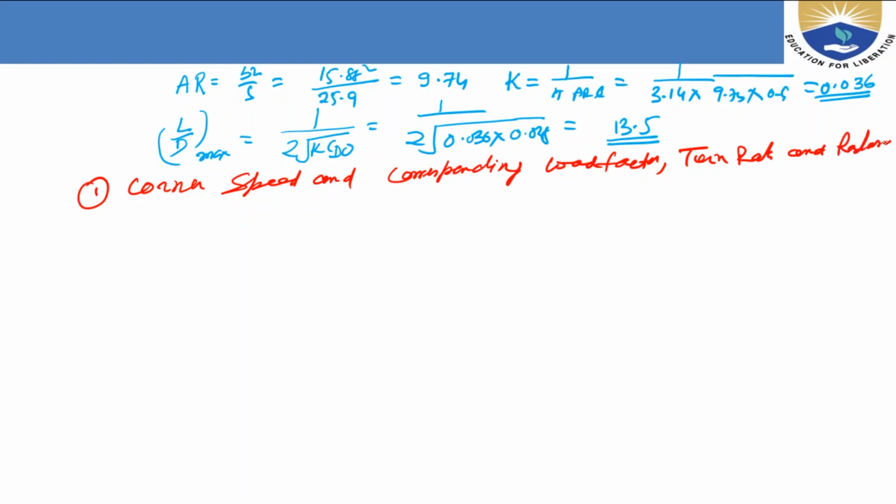These things we have to find out. I will start with the corner velocity. It is called V star and we know that it is the square root of 2 P max eta P divided by rho S into CD naught plus K CL square max.